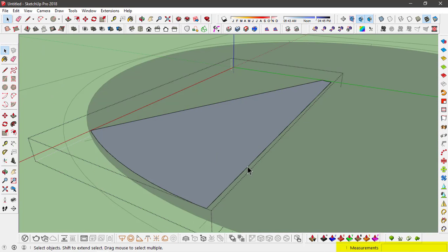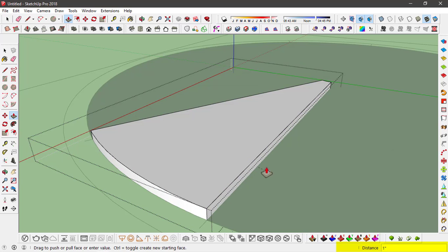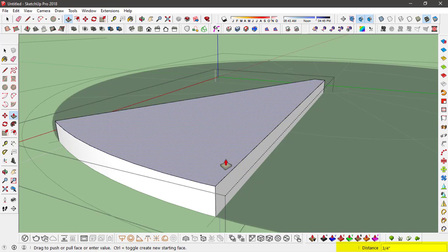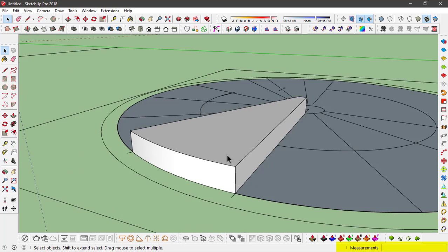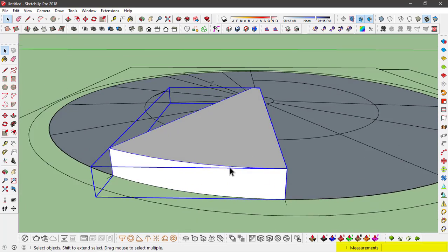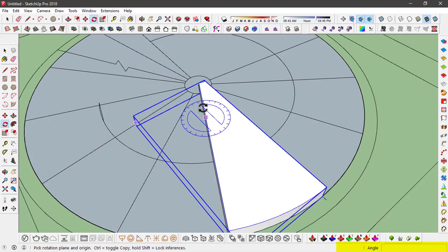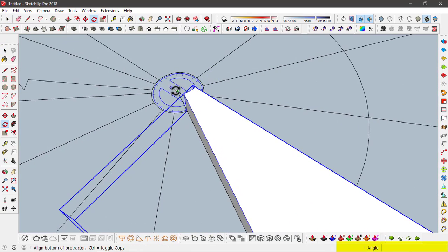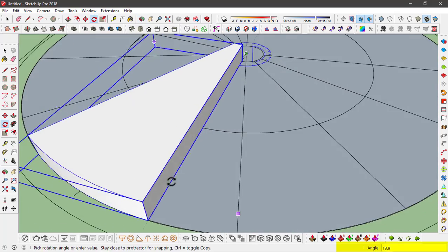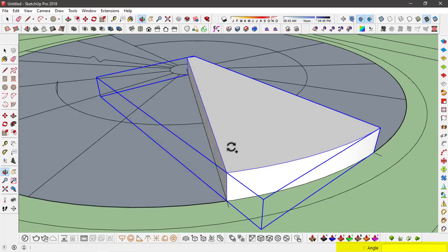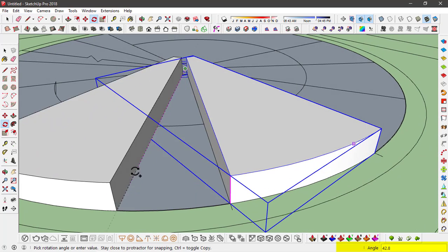And in this group I'm going to extrude this first to this ground level and over about 2 inches, so that the total height of this step is around 3 inches. And then go to the Rotate tool and make a copy of this, snapping to the middle point of the circle to this edge, and hit the Control key to make the copy onto the very next step.